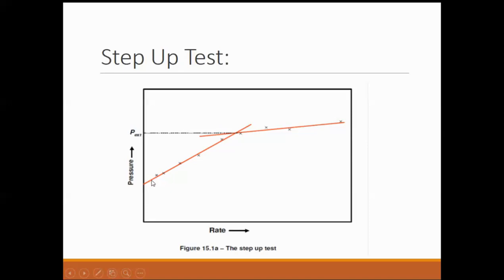Is there any impact of hydraulic fracturing on water reservoirs? Water reservoirs, I already told, there is no impact identified in India. And to keep it that way, we have to follow the government regulations. If you are designing a frac job and the way your wells are going to be drilled and completions designed, the conductor casing and the surface casing have to be properly laid and properly cemented, and you have to ensure that there is no communication between the water tank and the zone that you're going to frac, and ensure that there are proper barriers.